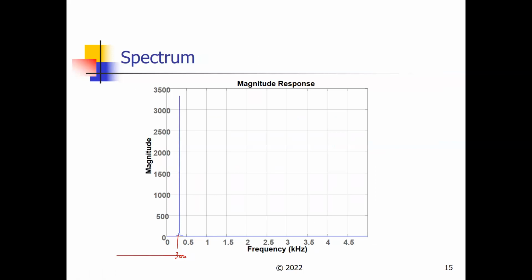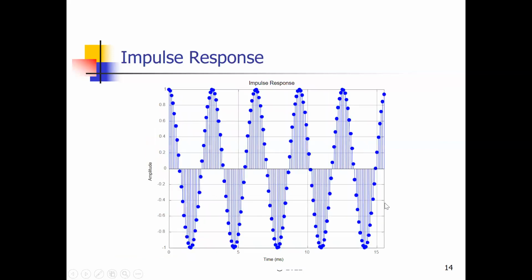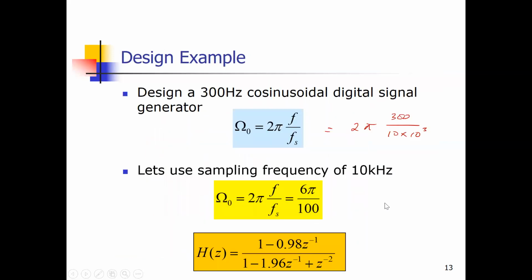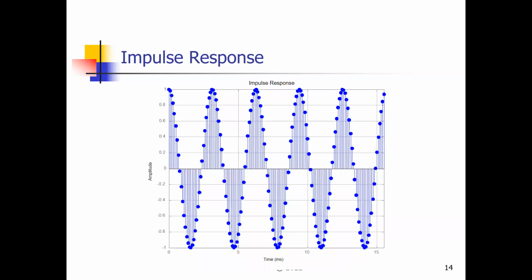In most cases, people tend to generate cosines instead of sines, although it's 90 degrees off. But for practical purposes, it tends to give you easier manipulation. Remember, if you were to go back to Euler's relationship, e to the j omega is cosine plus j sine, or cosine minus j sine, depending on what you're trying to generate.